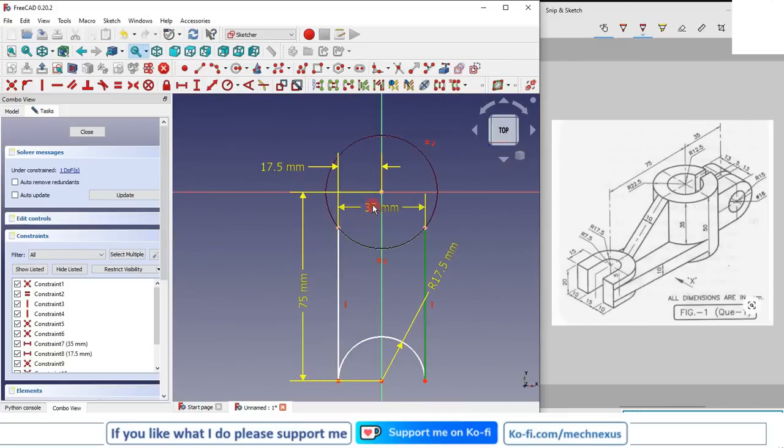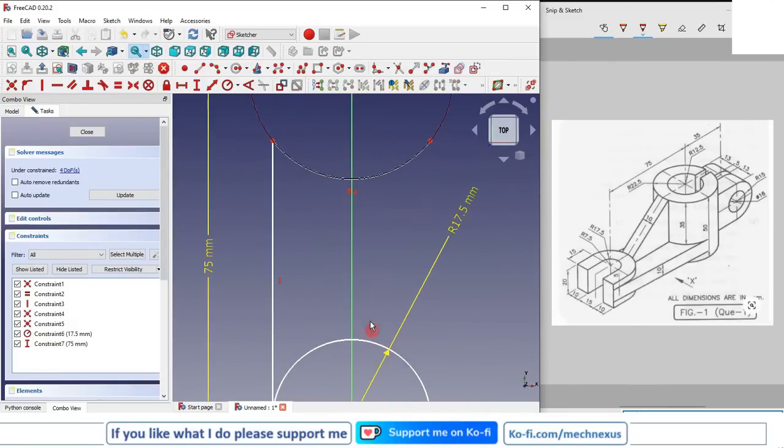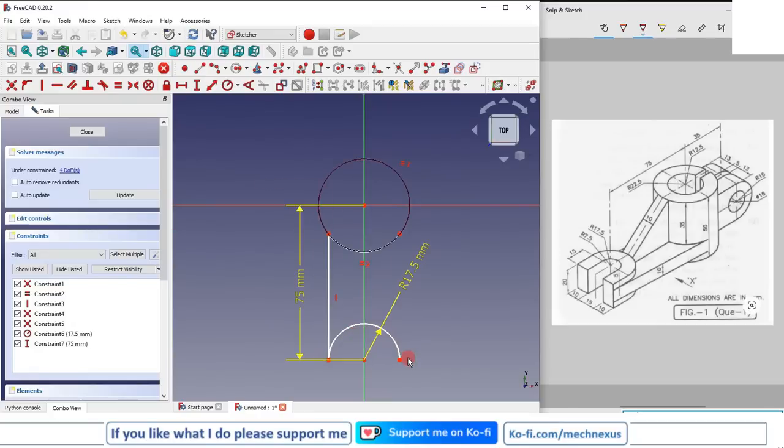So for this we will select this dimension and delete it. Delete this dimension, and this should not be vertical, so I will delete it, and it should be something like this. Now I will make it horizontal with my origin point. Similarly this one.